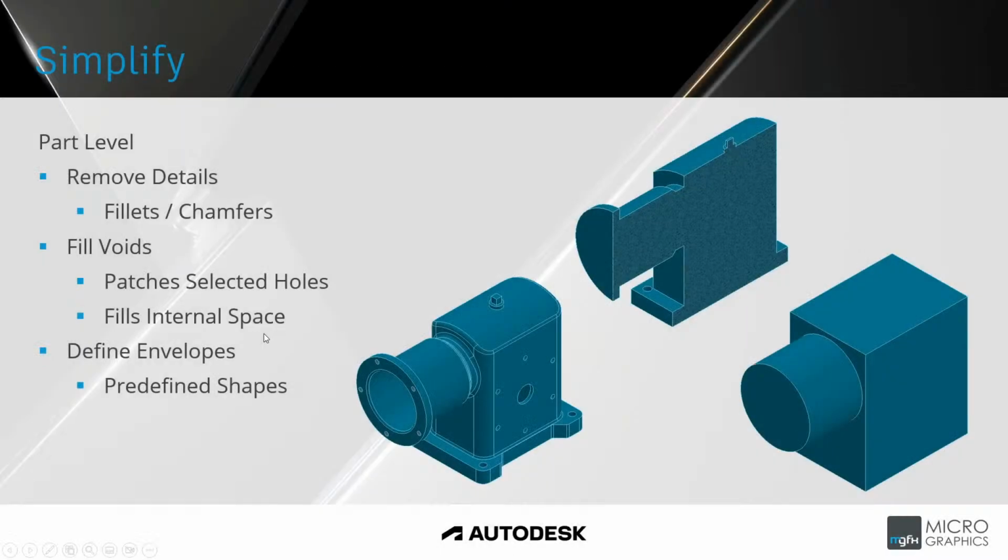Now going back to the presentation, we're going to look at an option called Simplify. Now, Simplify is a tool built into Inventor that allows you to remove geometry in a much easier way than manually going and suppressing features. Simplify allows you to remove details such as fillets and chamfers quite quickly, but it also allows you to pick surfaces to then create voids that can be filled.